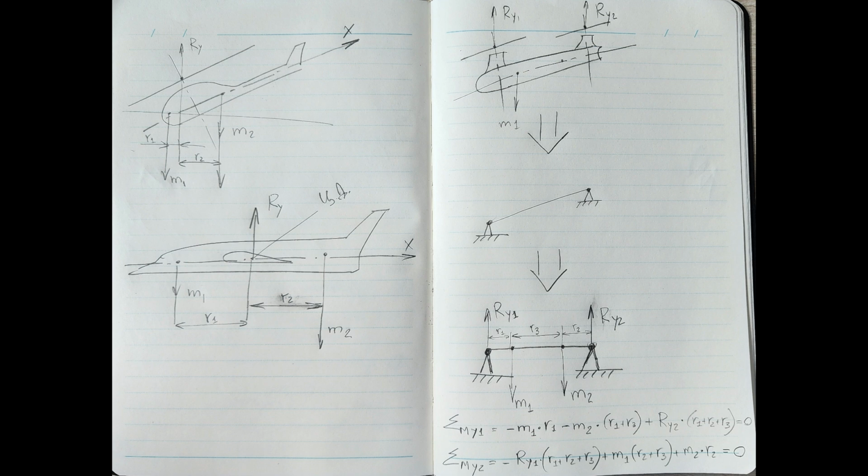I.e., we simply estimate the mass of the payload, the mass of the fuselage, the pylons, the systems and the power plant, place the load application center at the center of the frame, and select screws and electric motors based on this information.